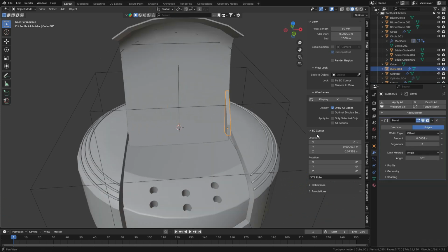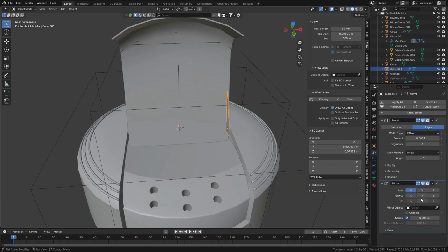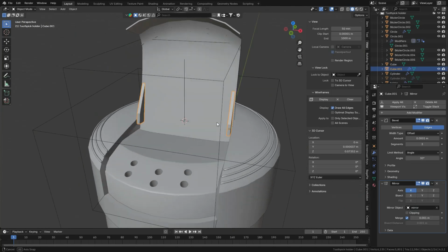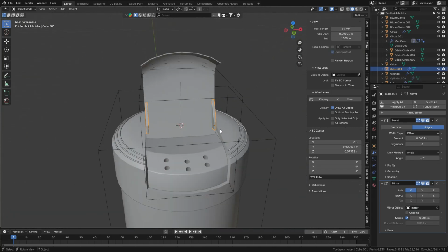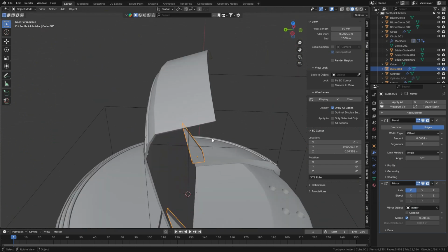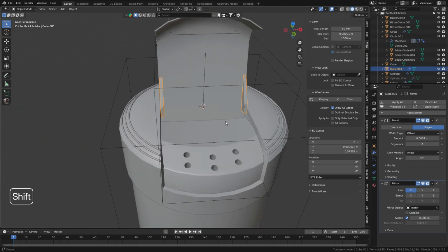Then we'll select this, add a mirror modifier. Instead of X, we'll select the mirror object, which is the empty we called mirror. Select it, and then we have it. So you have two hinges that are completely symmetrical. And realize that once we use this method, once we move one, the other one automatically moves, and this is great. Okay, so we have hinges for that.